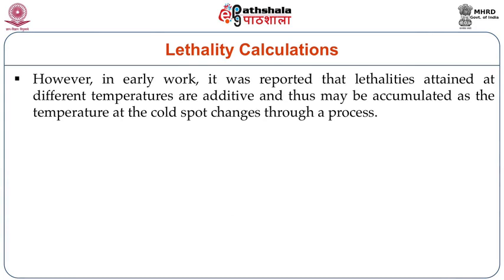However, in the early research work, it was reported that lethalities attained at different temperatures are additive and thus may be accumulated as the temperature at the cold spot changes through a process. Thus, knowing the cold spot temperature history, one can determine the rate of lethality at each time increment, plot the resulting data as a function of time and integrate the curve to obtain the equivalent lethality at the reference temperature. You can see the figure projected in the slide.